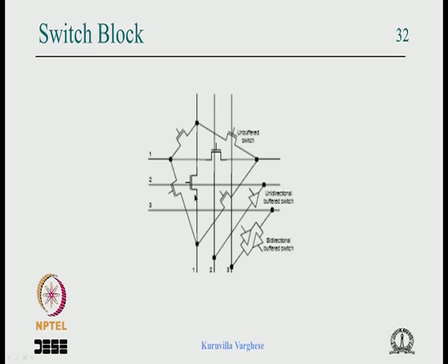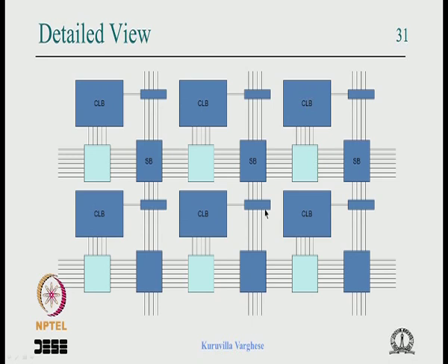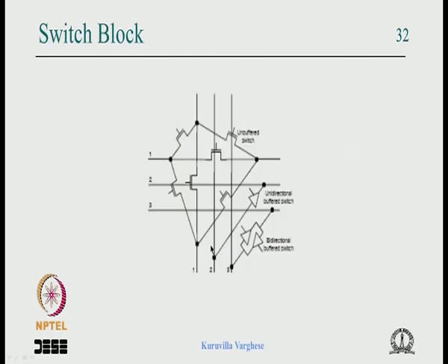And now if you look in principle, if you have a 3x3, this can be connected not only to this, it can be connected to this as well as this, and maybe yes, say each of these lines can be connected to 3, but sometimes providing all possible connections can make this very huge. So many times it's not that a single wire is connected to every other wire and so on. Okay. Particularly there may not be any connection between the vertical and vertical wire, there is no need, because we have seen the output is coming to all vertical lines. So normally the vertical lines are connected to the horizontal wires, but here when it comes to a switch box, this part needs to be connected to this vertical line to cut through. Okay. So that connection is required, that is what is shown here. So there is a vertical connection here, okay, and a horizontal connection here.